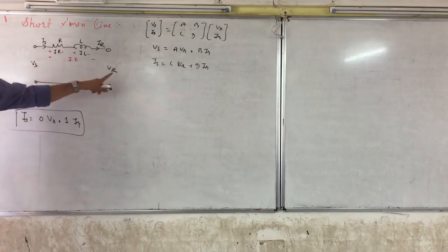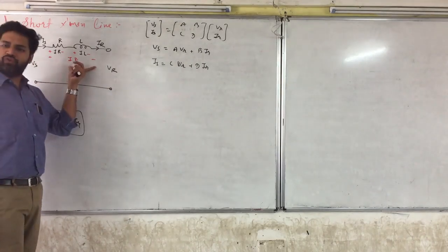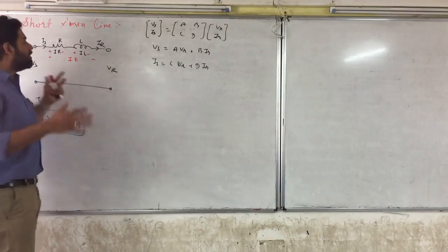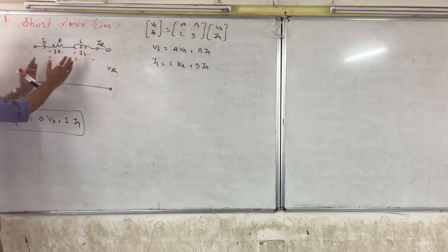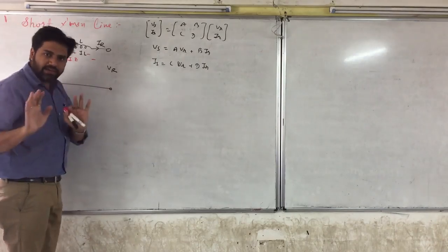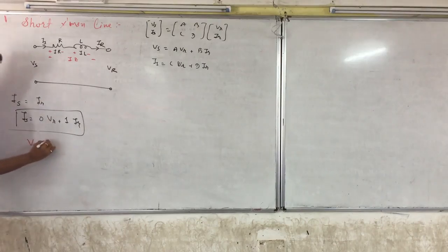Vs is more in comparison to Vi, because from Vs I'm sending, I have this much drop, and we're getting Vi. Is it clear? Fine. So whatever 100 volts I have and 10 volts drop I have, I'm getting 90 volts. Is it clear? So we can say that I have Vs voltage minus Iz drop, and that is giving me the value of Vi.